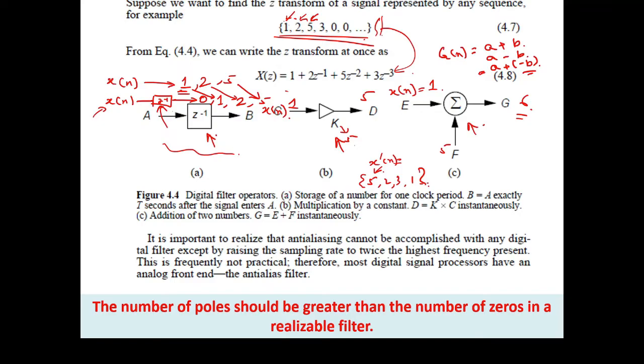Next, when we are trying to design a filter, we have talked about anti-aliasing. We have to realize that anti-aliasing cannot be accomplished with any digital filter.